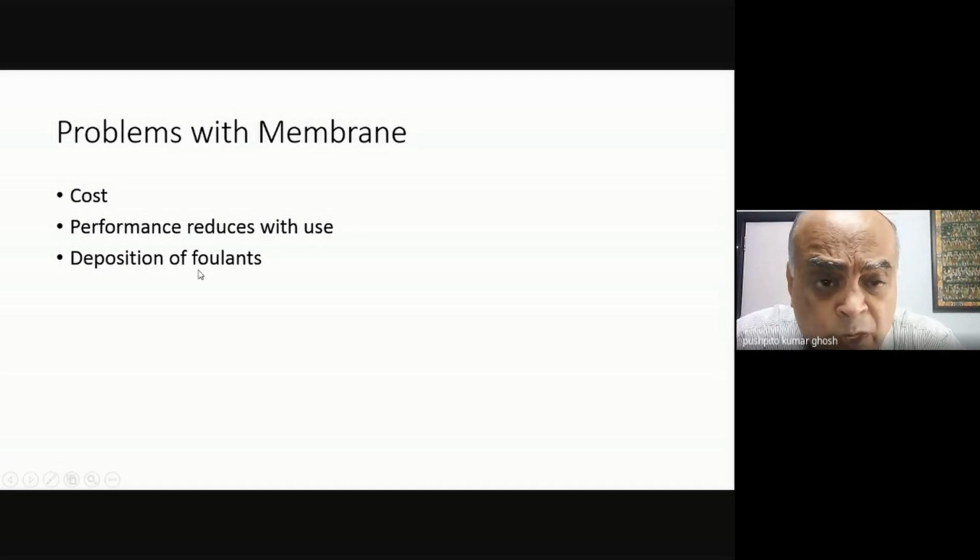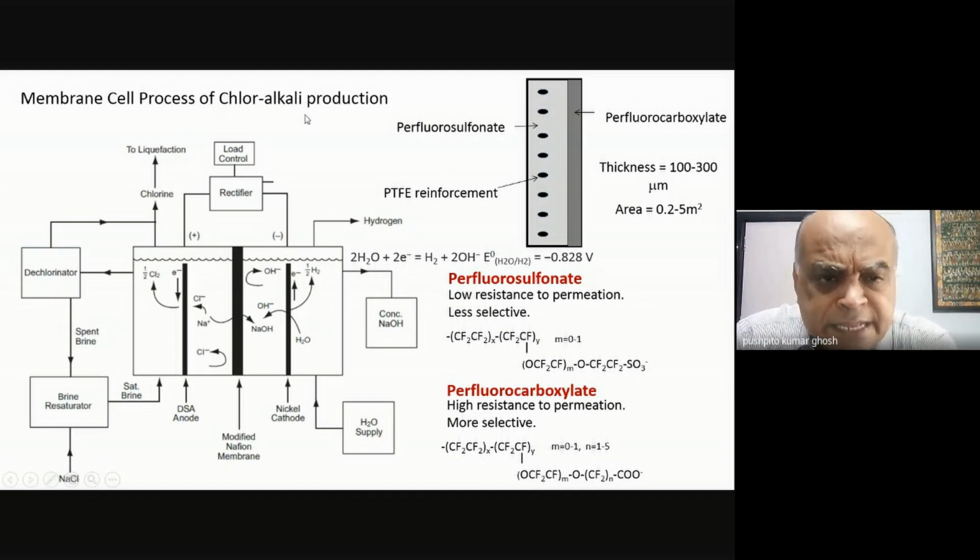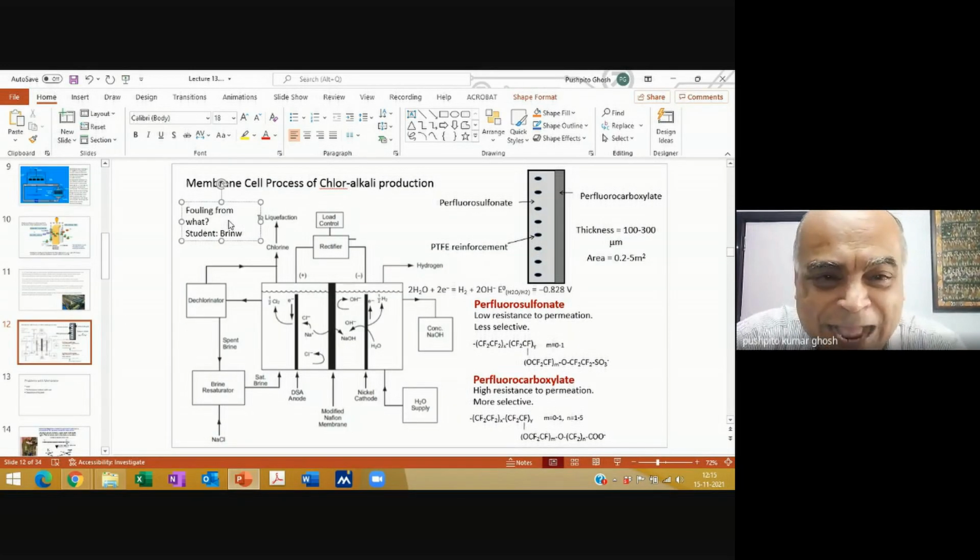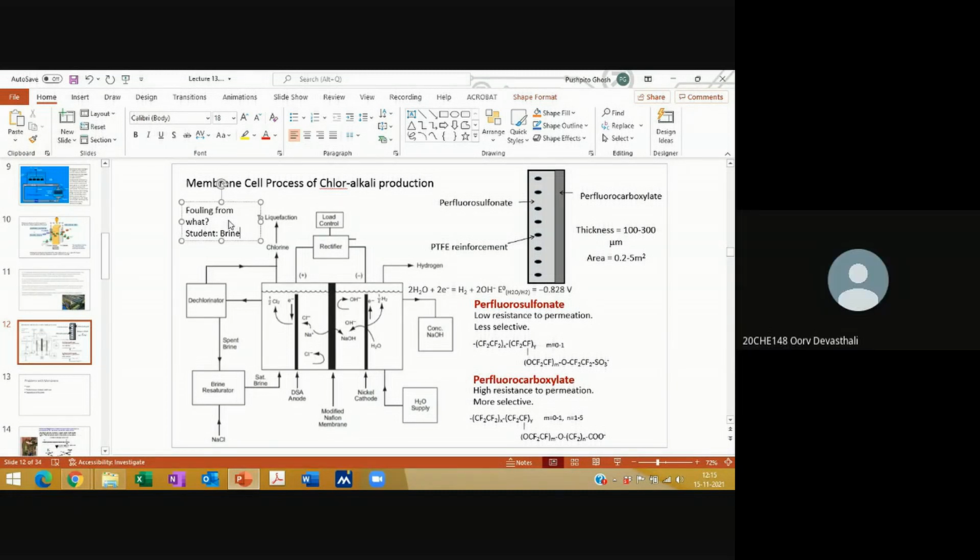And if they start fouling up, their performance will go down. Now, let me ask you, in this system, can you see anything that can possibly foul up the membrane? Anything? Think hard. Brine. Brilliant. And what in brine? Sodium chloride solution concentrate. The magnesium salts. Correct.